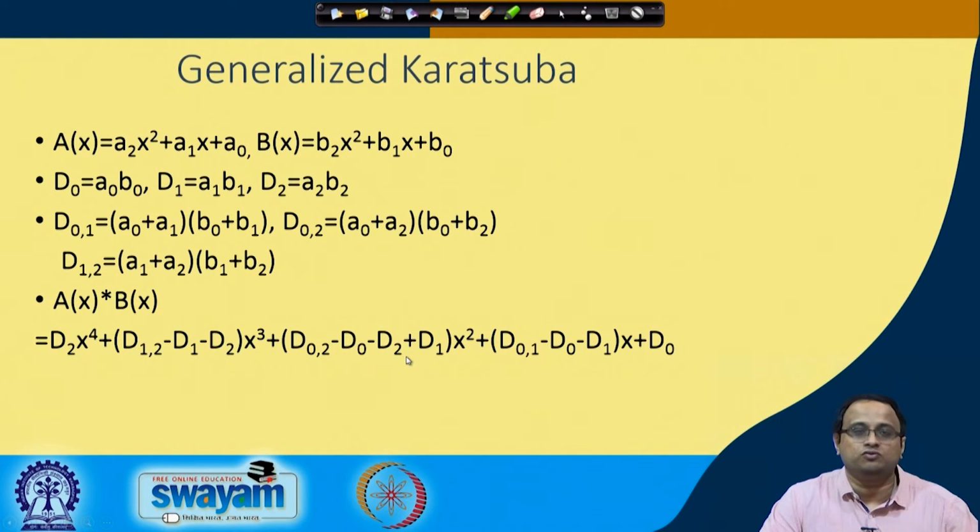Now if you remember the old discussions that we had on the lookup table structure for the FPGA, it already has fixed inputs. That means if you are not using all 4 inputs, for example in a 4 input lookup table, then you are underutilizing the lookup table. That is why general Karatsuba seems to utilize the lookup tables better, because it always has this number of input arguments for each of these terms.